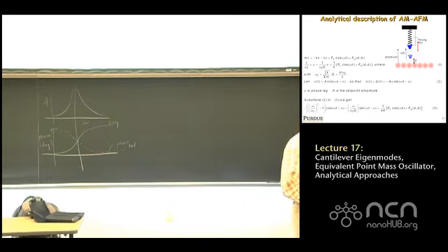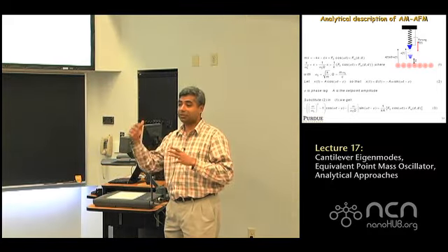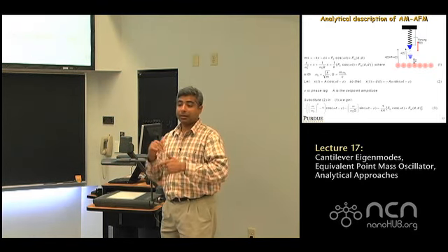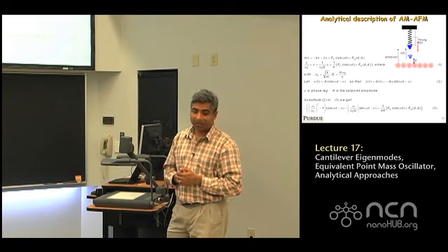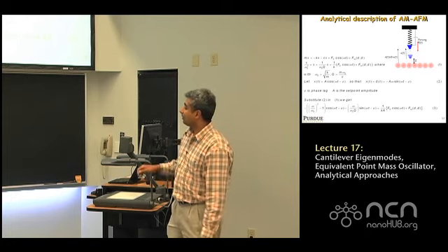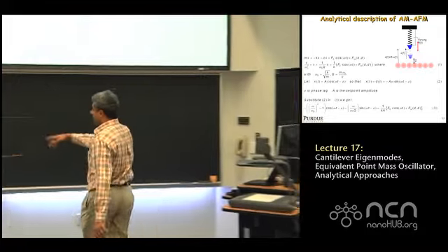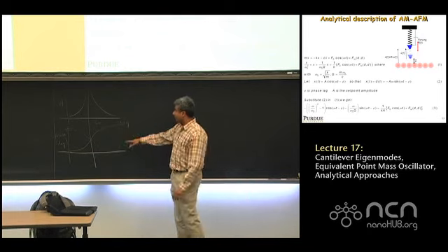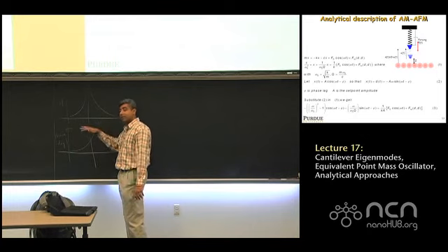So in other words, we use the fact that we know theoretically, when you're withdrawn from a surface, you do a tuning curve. I've shown you the transfer functions. You know how it should behave. And so see what you get, and based on that, judge if it's lead or lag. So when the AFM company plots the phase in degrees, it can be shifted. Yeah, that's completely true. That's why I did not show any number on here. And so usually, the first thing you do is to look at the generic shape. Does it go down or up across resonance? If it goes up across resonance, it's phase lag. If it goes down, it's phase lead.